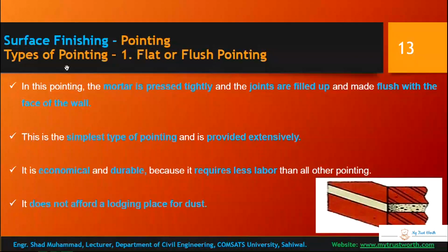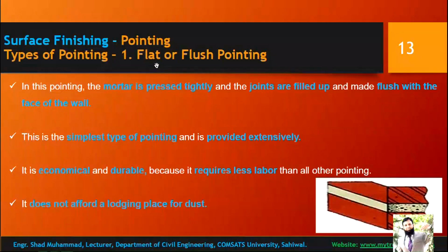Surface finishing pointing. We were discussing types of pointing. In types of pointing, we have flat or flush pointing. In this pointing, mortar is pressed tightly and the joints are filled up and made flush with the face of the wall. Mortar is pressed tightly.